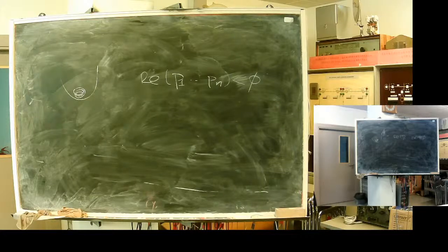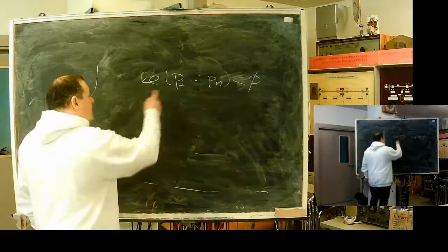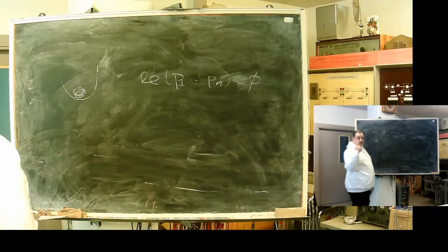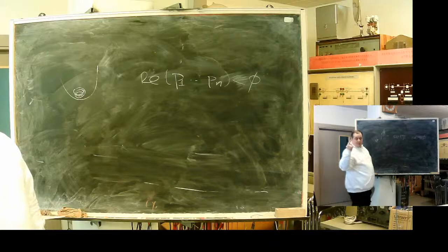If we have a heat, the system receives some energy from outside. If all roots have a negative real part, energy will dissipate, go to heat or something like this, and the system will go at last to a stable condition. If any one root has a positive real part, this means that at this frequency, the energy balance will be positive and the system will go up to destruction.